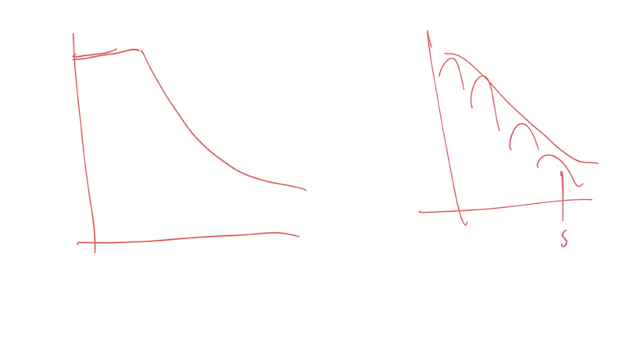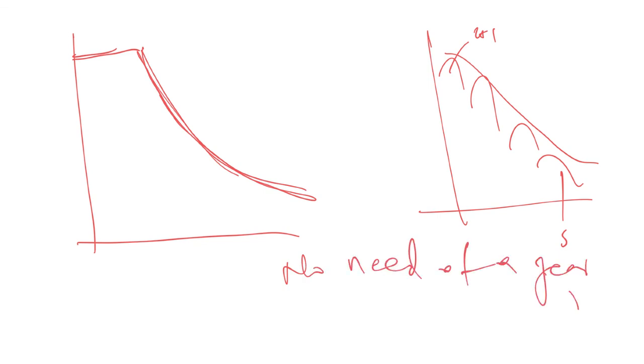Okay, so now if you look at the torque speed profile of the electric machine, it has a similar shape as we observed with the gears. Remember, with the gears, it was gear number 5, gear number 1. So we have that behavior already in just the characteristics of the electric machine. And that is why you don't necessarily need a gearbox. No need of a gearbox.